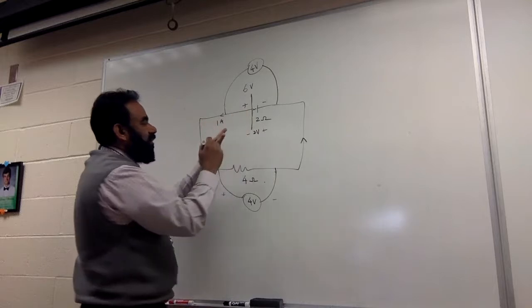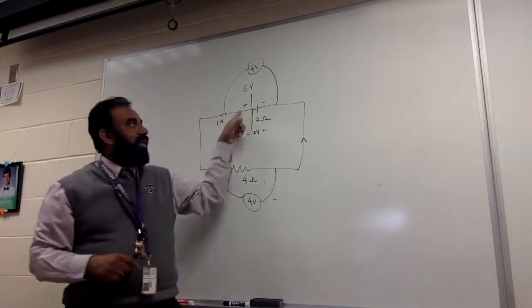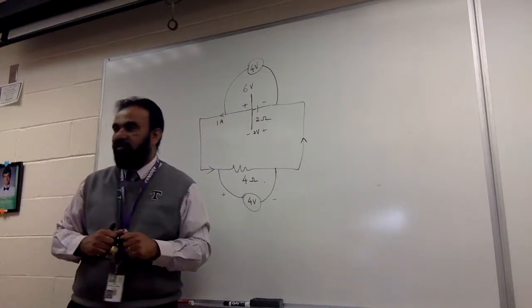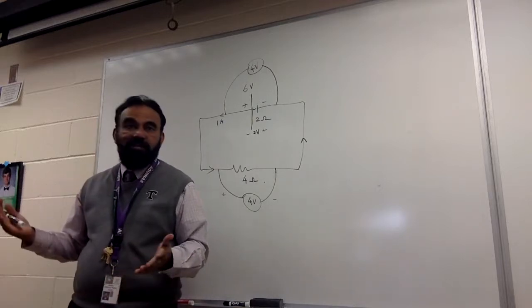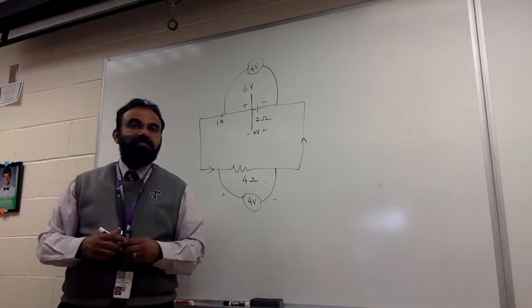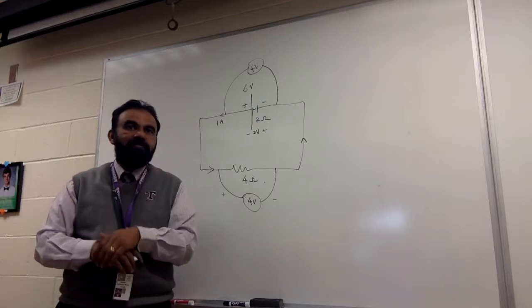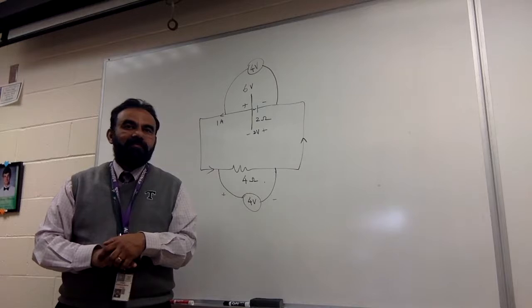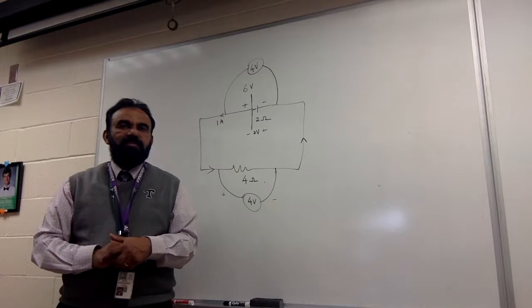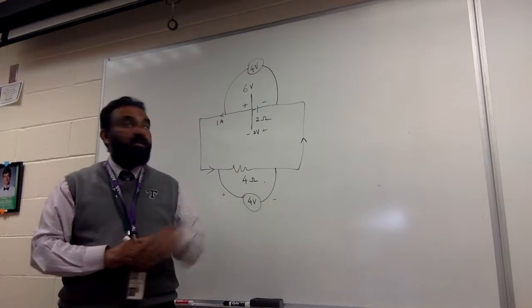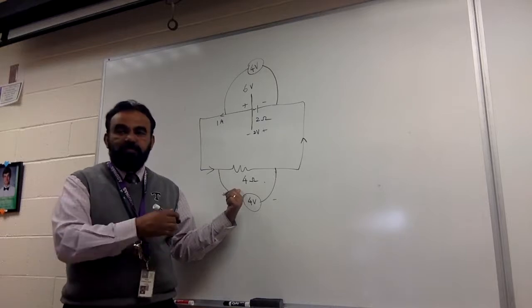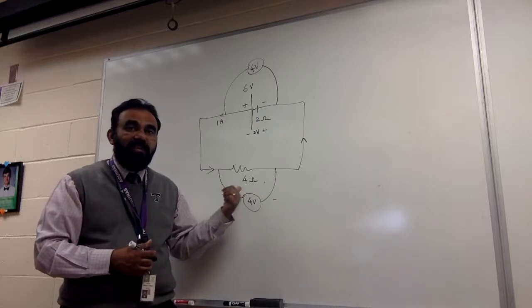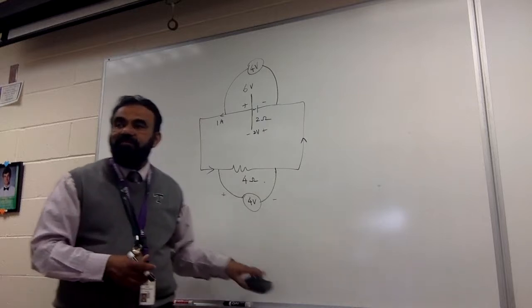The voltmeter is looking at the cell and saying, oh, I have plus 6 here. Oh, wait a minute, there's a minus 2 inside. So take it off. Get it? So if you had a 6-volt battery, and if companies wrote the potential difference on the batteries instead of EMF, they would be writing 4 volts. They never write the potential difference. That depends on what you're connecting to. That's my next example. I'll show you, if I connect something else, how it changes.